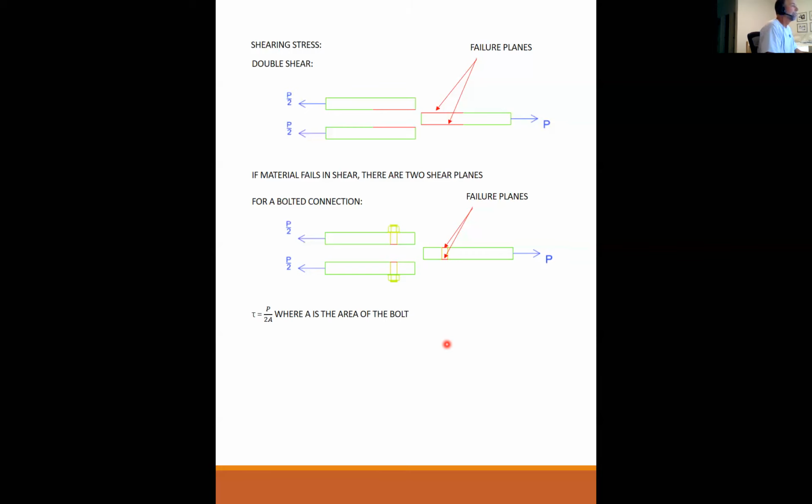So your steel design course, your concrete design course, those types of courses, ultimately comes from a code book called ASCE 7. And the current year that we're working on now is ASCE 7 year 16. And that's where in chapter 2 of ASCE 7, all the load factors come from.